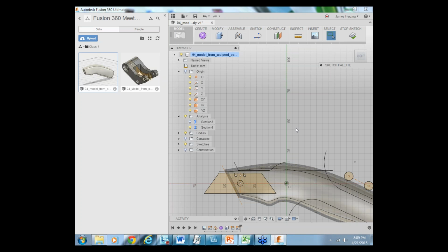All right, so now we're going to make a second line. To do that, we're going to right click and choose the repeat line command. That's just another way to quickly use a command that you previously just used. So instead of going to sketch line, we can just right click and choose repeat line.